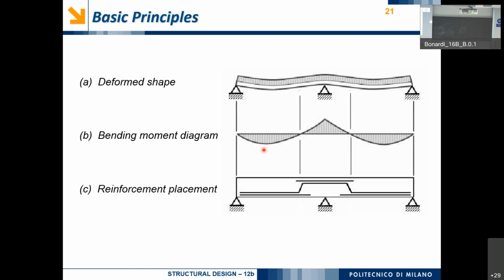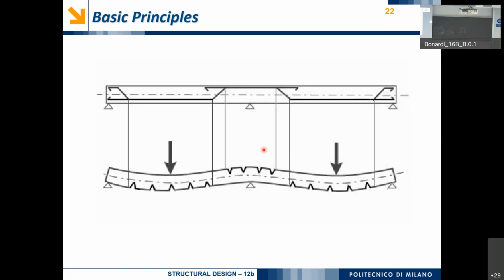Now it is not that used because it is more expensive, but the idea is to use the same bars that walk along the path. It's crazy, but this is the idea. So that's what we do. We put our reinforcement at the top where we have internal supports and at the bottom elsewhere.